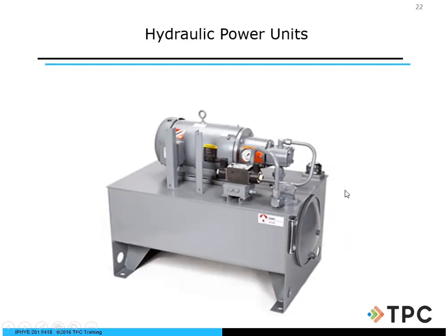But you just don't want to go over there and change it because the PM said so. So you can do an oil analysis. That's more of your predictive maintenance technologies. The oil analysis is going to let you know what is failing upstream of your system, because whatever is in your system upstream from the reservoir is all going to come back to my reservoir, to my tank. If you do that oil analysis, you'll see what is made up of tin, aluminum, etc. That way you'll be able to identify, well, this component upstream is failing, so I need to be more proactive and take care of that.